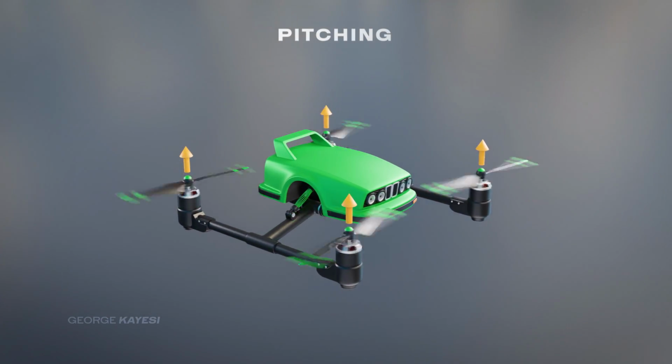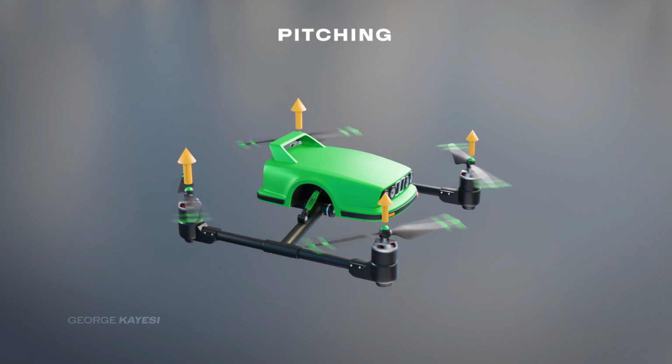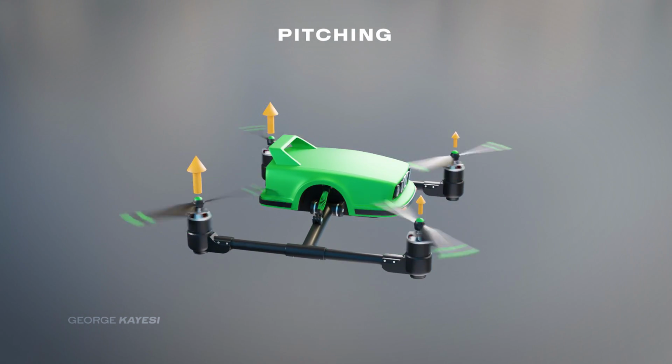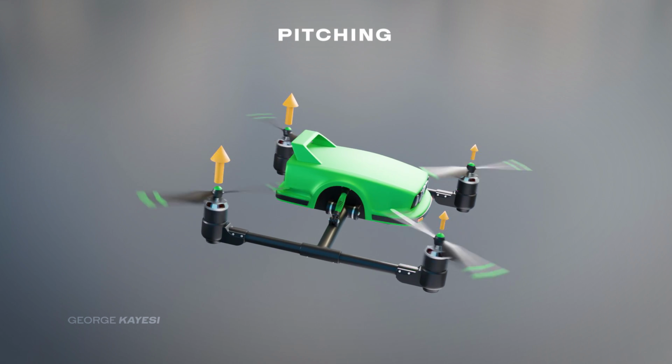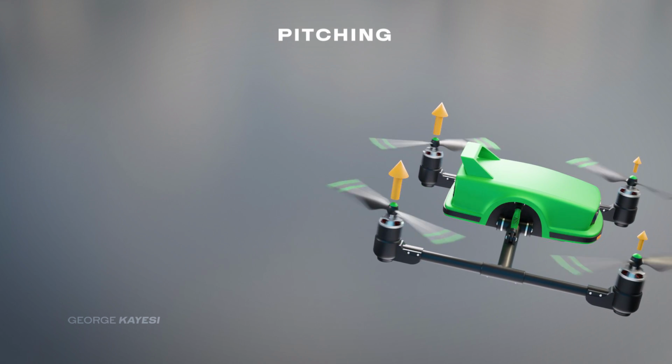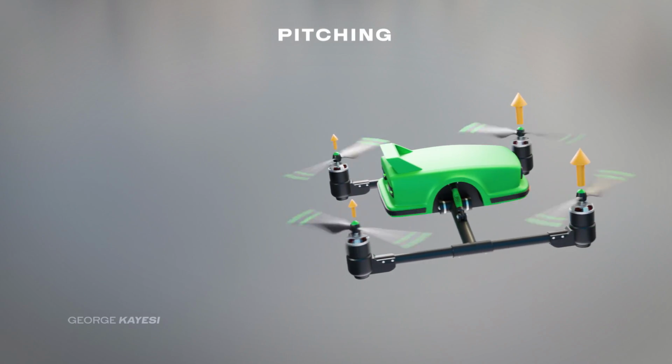To pitch forward, the power of the two back motors will increase, and power to the two front motors will reduce. The result of that force will pitch its nose down, and the quadcopter will move forward. To pitch backwards, the quadcopter will simply reverse the process.